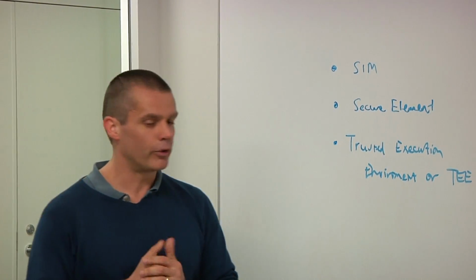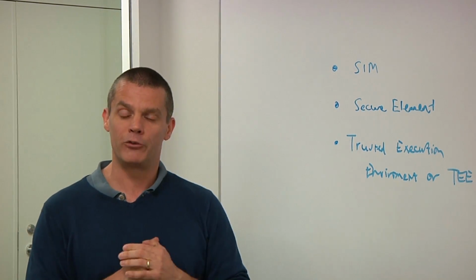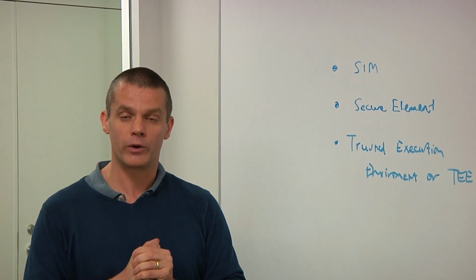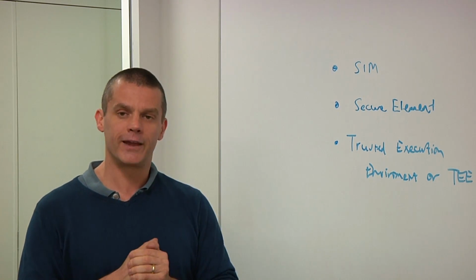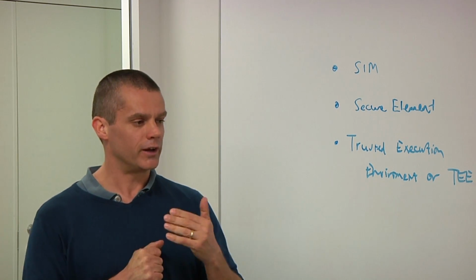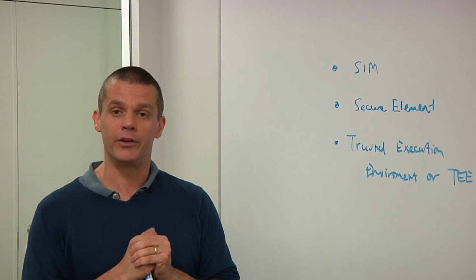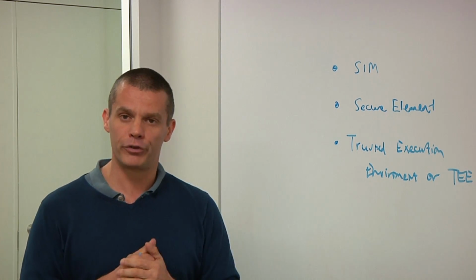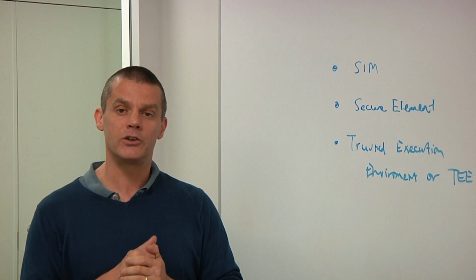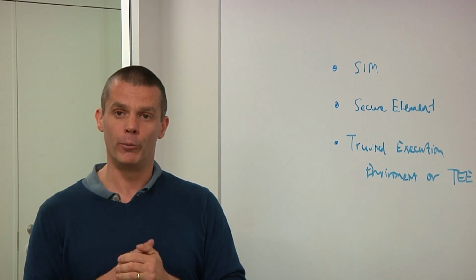Sure. So the emerging buzzword that you'll hear in this space is what's called an integrated root of trust. This would be something that would reside on a chip like the application processor and would work alongside, for example, things like TEEs that give software protection, but really give you something that's a foundational security component on the main chip that locks down a root of trust against all forms of attack.